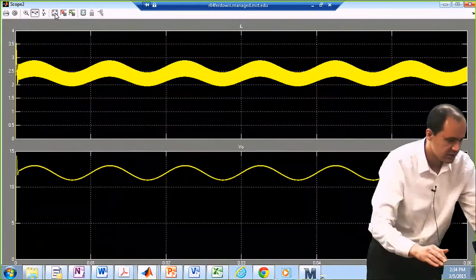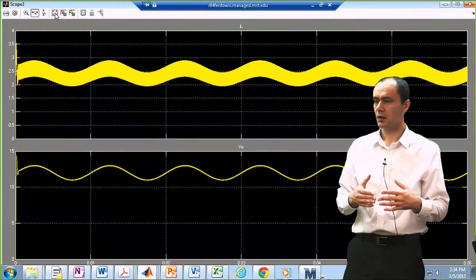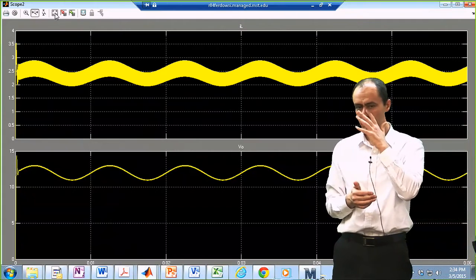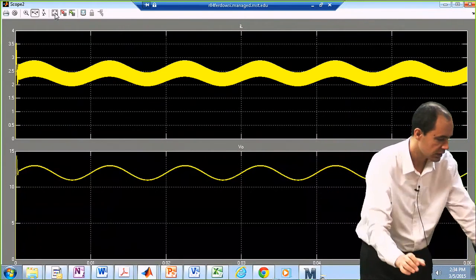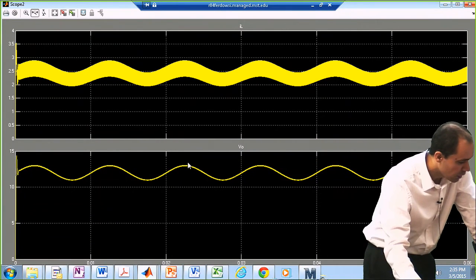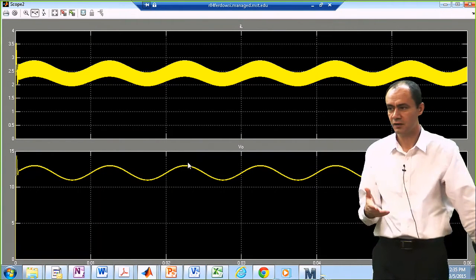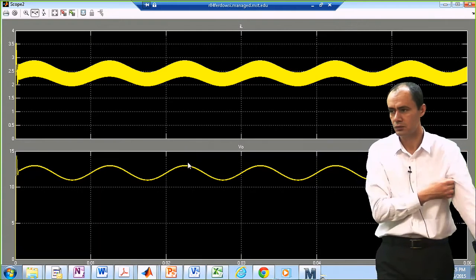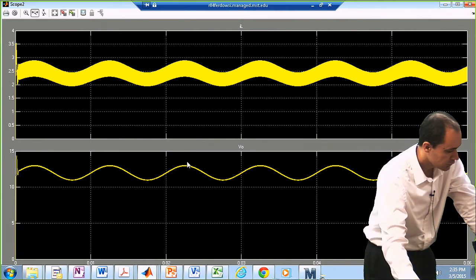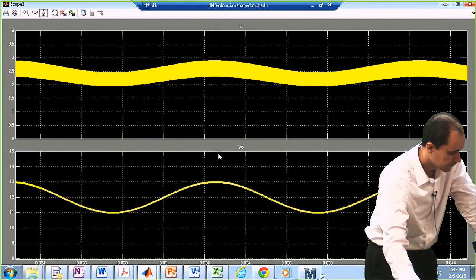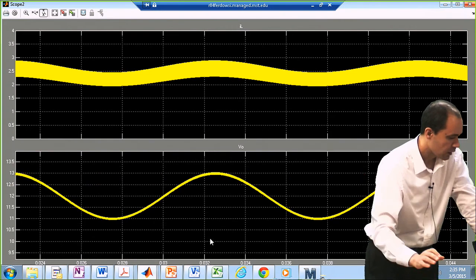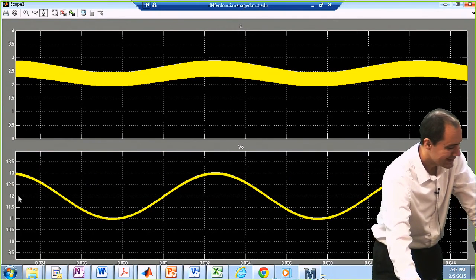Well, obviously, this is an open loop behavior. The input voltage is perturbing, but the duty cycle is still constant at 25%. So technically, I'm multiplying the input voltage by 25%, and that appears in my output voltage. So you can see my output voltage has a ripple.